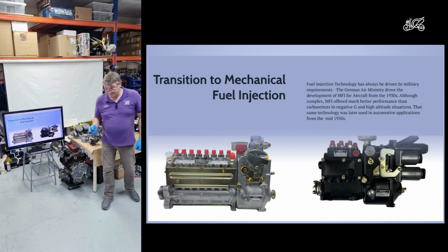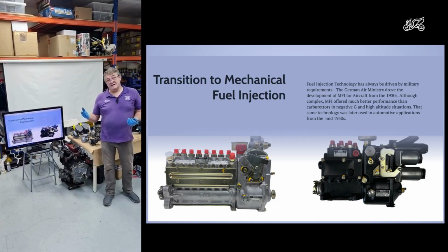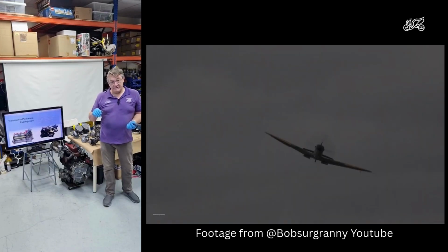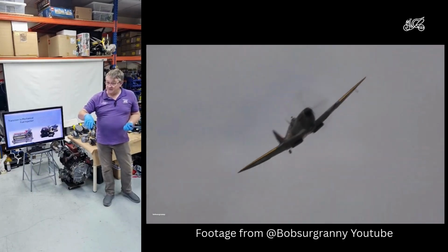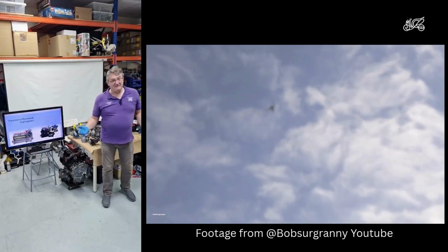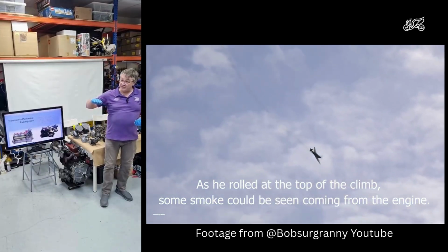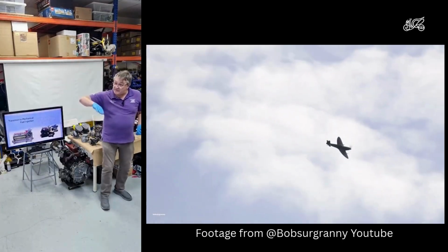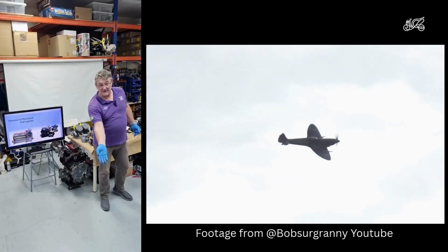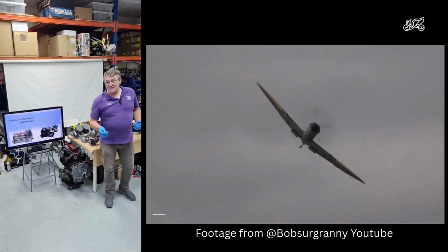They were wrong. So the Second World War started, and the Germans soon realized that a Spitfire would not perform in a dive, because as soon as you dive the Spitfire, the carburetor would flood, the mixture would go rich, the engine would stall. So the only way for a Spitfire to dive at the start of the Second World War was to flip it over. So they had to flip over and dive upside down so that their carburetor still worked. And so this was a serious thing.